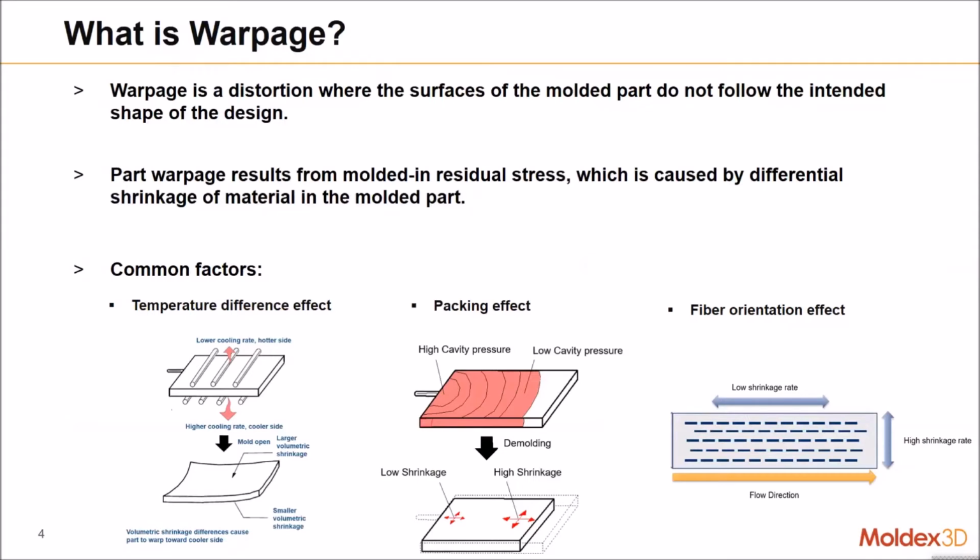Okay, so there are three common factors that produce the warpage problem. The first one is the temperature difference effect. An imbalanced cooling channel design is a common reason to cause the warpage problem. So in this picture, you can see 4 cooling channels are placed at the bottom of the part.